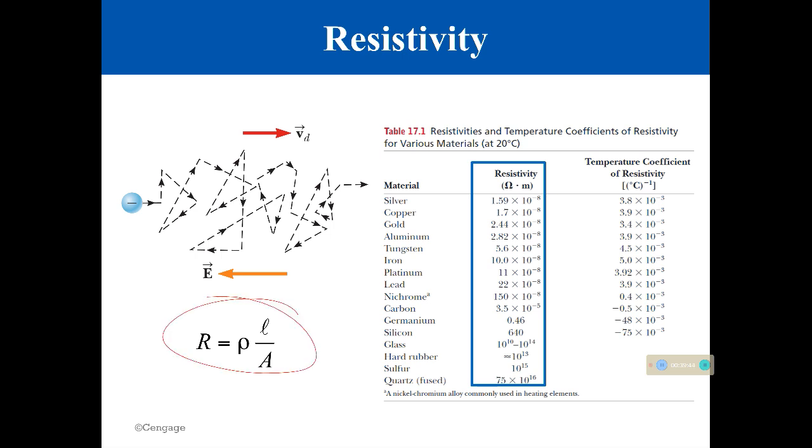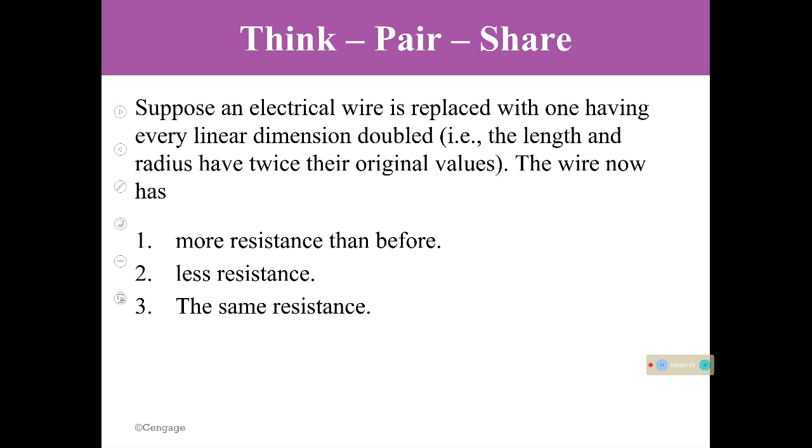Okay, so there's the equation that we just made a second ago, and we already discussed the reasons why. If I wanted you to calculate the resistivity of a material, what would you do? You'd probably go find resistance. You'd measure the length. You'd measure the area. And then we would graph once again, trying to get a slope for the resistivity in that particular case. I'd probably move I over here, and I'd measure delta V, and I'd measure I. Knowing those values, that would be your slope. You get the whole picture.